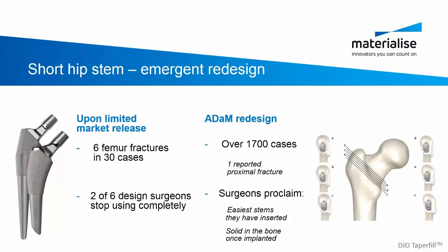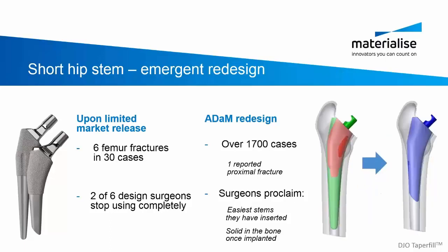So they worked with us with statistical shape modeling to start to look at what is their patient population and perform virtual fits of these implants across their patient population. And what we could learn is, if you actually look at this dark red region here, there was a very high interference fit with a subset of the patient population. And so upon looking at that, we could help look at a redesign, taking into consideration all of this patient population information, slightly lengthening the shaft of the implant,